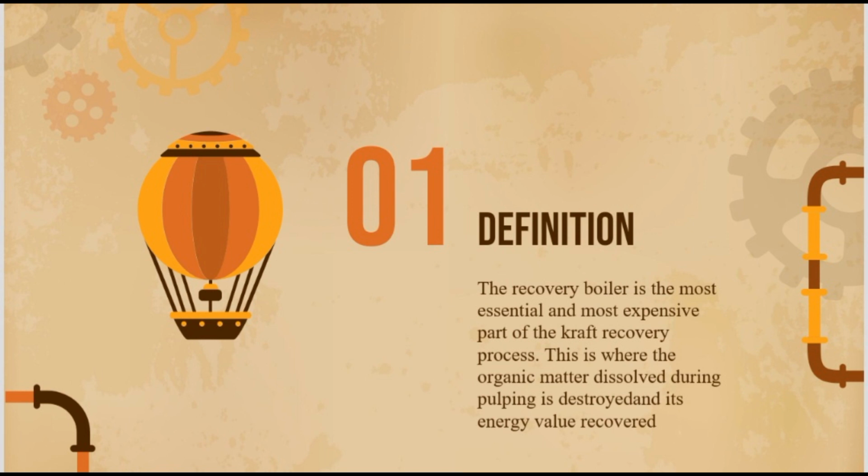To understand any combustion process, it is important to understand that complete combustion requires an adequate supply of air, an adequate degree of mixing between the combustible material and the air, a temperature high enough for the reaction to occur, and contact time at a temperature sufficient to allow combustion to occur. These are the classic three T's of the combustion process.